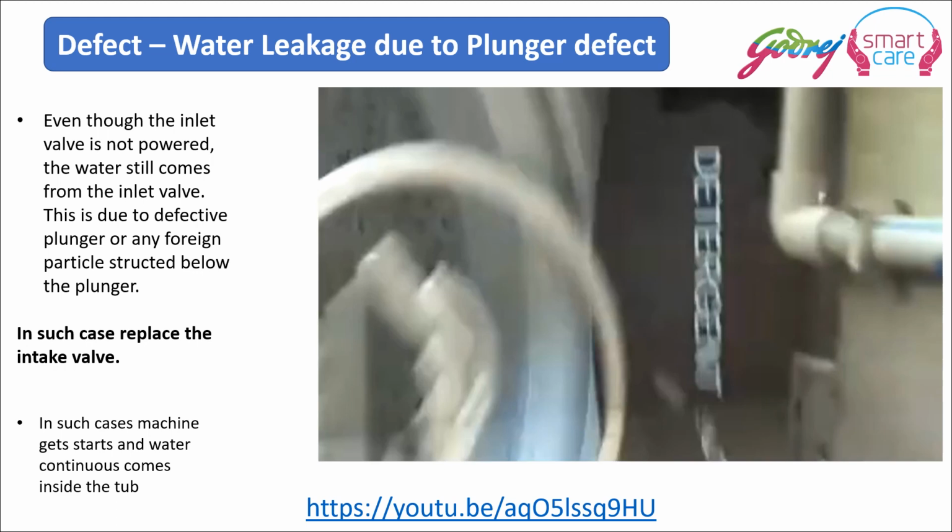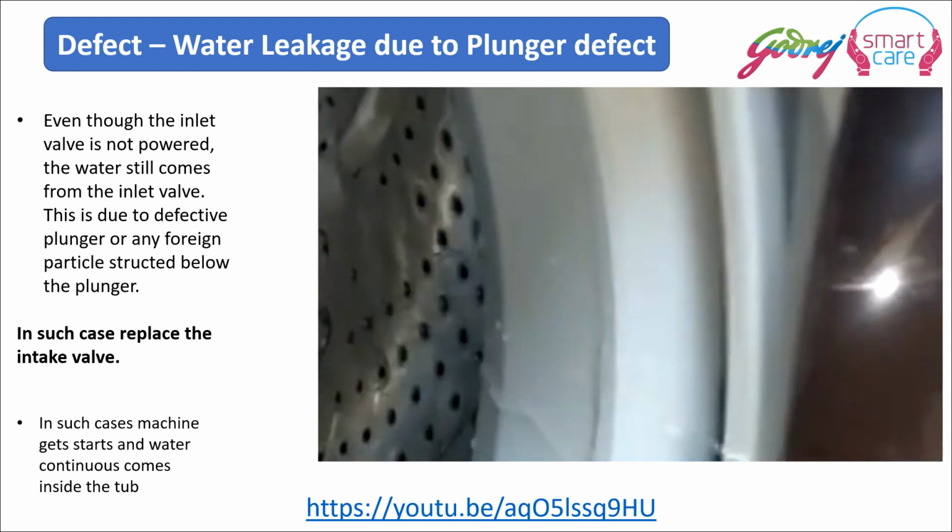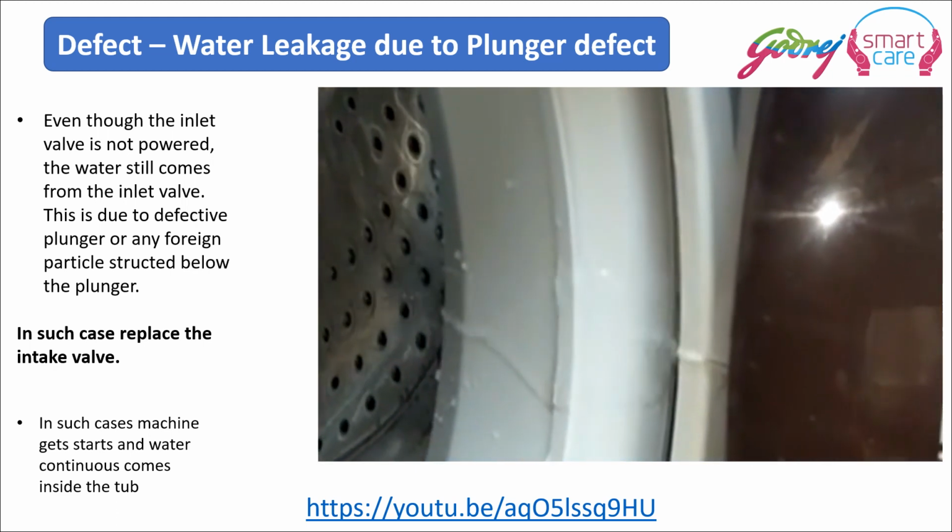Even though the intake valve is not powered, the water still comes from the intake valve. This is due to a defective plunger or a foreign particle stuck below the plunger. In such cases, we have to replace the intake valve. In such cases, the machine gets started and the water continuously comes inside the tub. Here is a small video for ready reference.